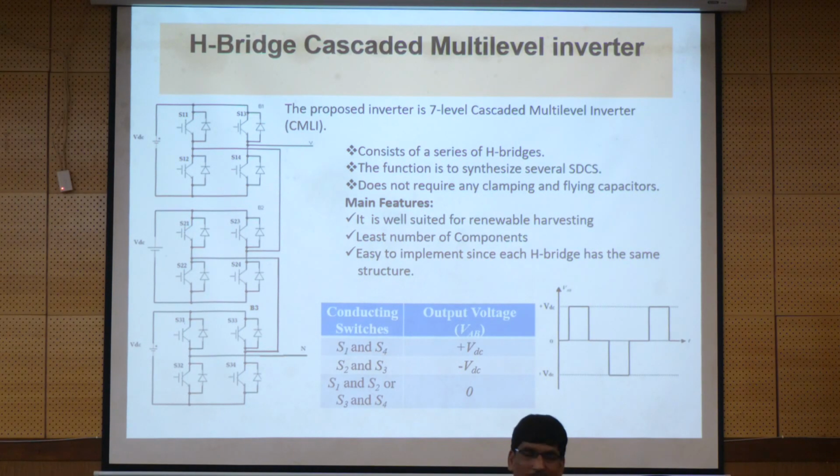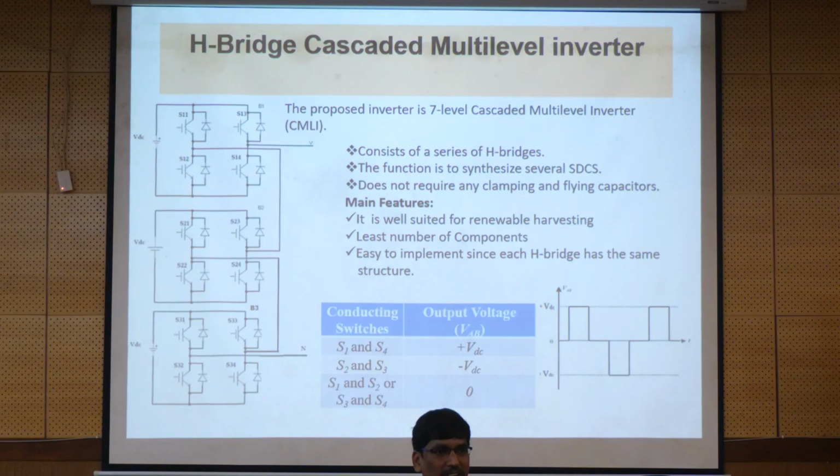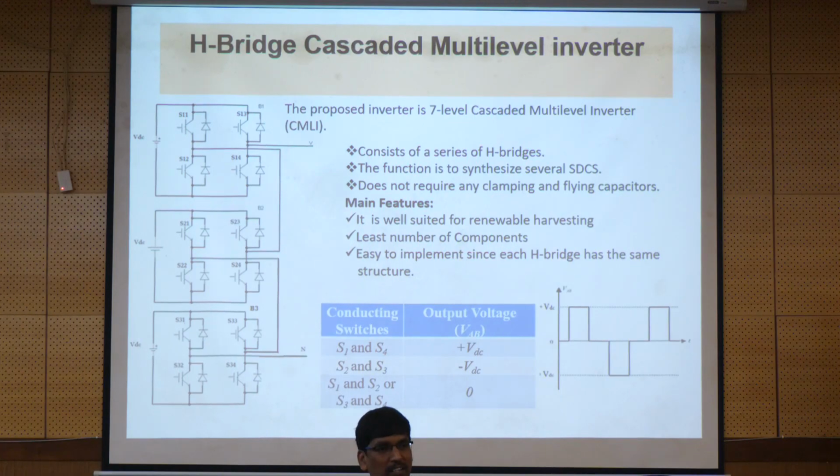When it comes to the AC machine, it is the frequency and the voltage. We talked about it in the previous session. In the DC case, just increase the voltage and you can increase the speed. Mostly in train applications you will see DC series motors. For power generation and some industrial applications, they make use of AC machines. There you require variable voltage and variable frequency. Here only the DC voltage.